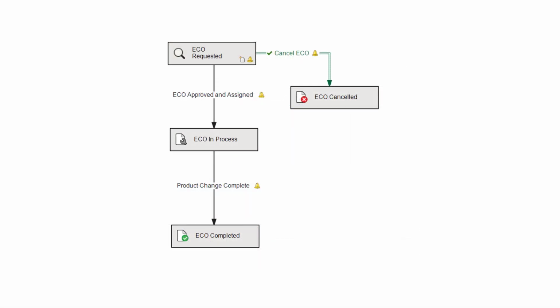These references are key in automating state changes for all documents that need updating. When the engineering change is complete, it is transitioned through the workflow. Not only can it change the state of the ECO document, but it can also transition our reference files as well. This is done with a little transition naming trick. You can create multiple transitions with the same name and conditionally allow documents to flow through each transition. This is extremely useful when you want to perform certain automated tasks on some documents, but maybe not others.